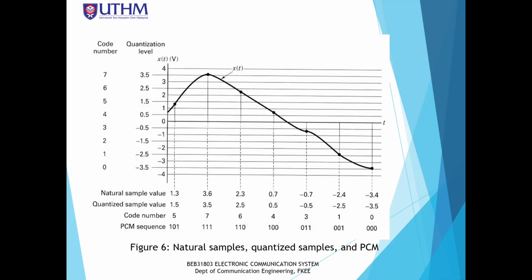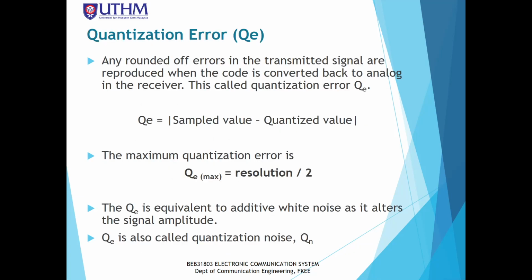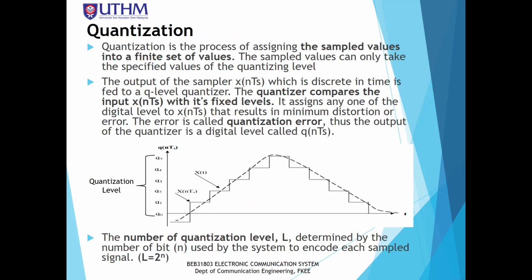What you have learned is the formatting process in order to produce a digital signal. From analog, you want to produce a digital signal. First of all, you need to do the formatting process, which is done within the analog to digital converter. I think you might be familiar with the word ADC. ADC is the analog to digital converter, which does the conversion from an analog signal into a